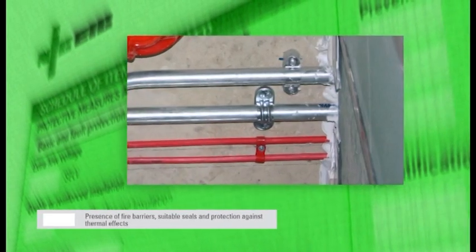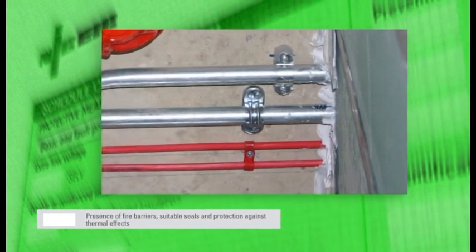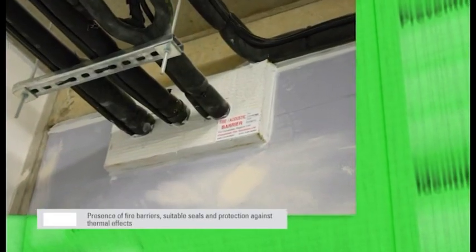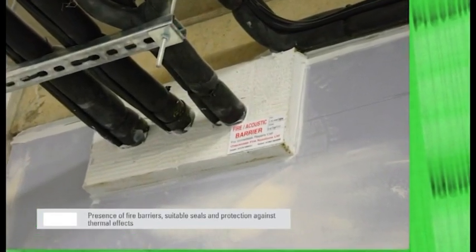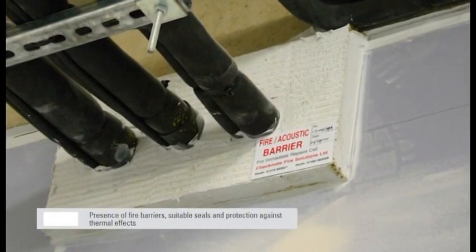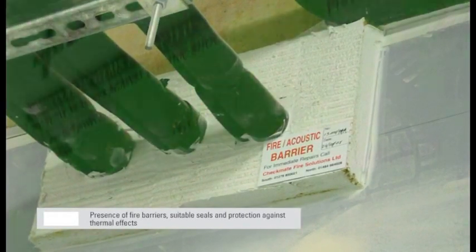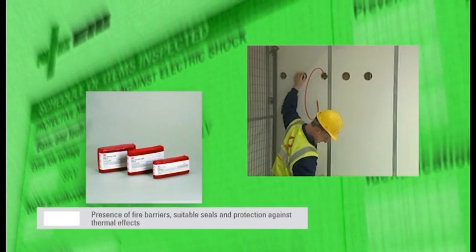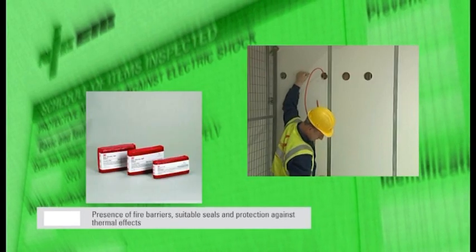Presence of fire barriers, suitable seals and protection against thermal effects is fairly self-explanatory. Where wiring systems pass through walls, it is vital that any gap surrounding them, and also any gap within them, which could allow fire to spread from one part of a building to another, is filled or blocked with an appropriate material having a fire resistance of no less than that of the surrounding building material concerned. The internal use of a fire barrier may not be necessary if a non-flame propagating wiring system is used.